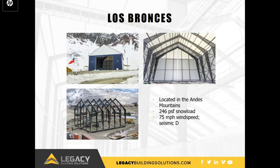So how does the fabric hold up to heavy snow? This particular building is in the Andes Mountains of Chile and carries a design snow load of 246 pounds per square foot. You can see the secondary bracing, which gives the building additional strength to accommodate the snow load plus wind speeds of 75 miles per hour. In addition to snow and wind loads, the building is also designed to handle significant seismic loads as is required in Chile. It's designed for housing and maintaining large mining equipment, so providing a protected area for workers is a primary concern for this facility.